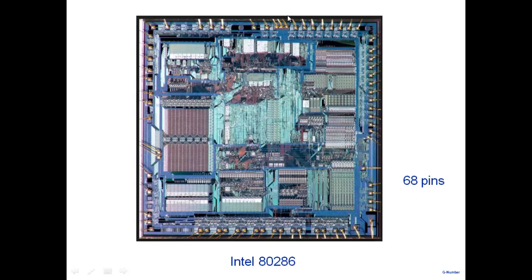And that's how you have it there. So in this case, as you can see here, there is a ring of pads here. And there are 68 pins that are distributed around the pad here. Right? And so this is called the pad ring. And the inside is what is called the core of the IC, the chip core. Okay, so that's the core of the IC here, and there's a pad ring here.